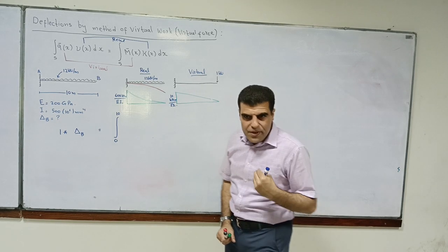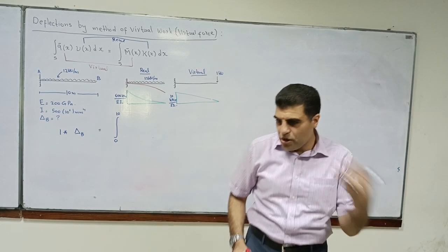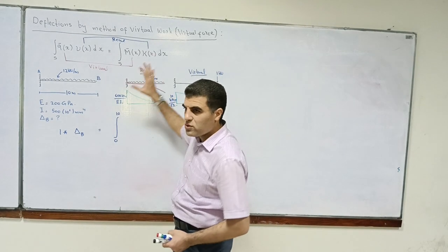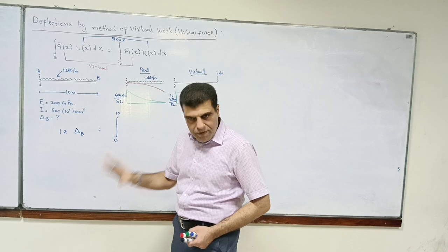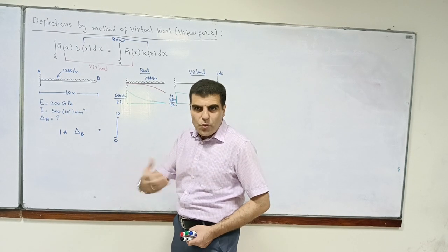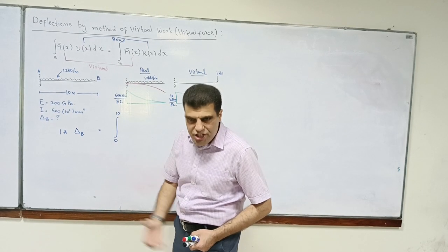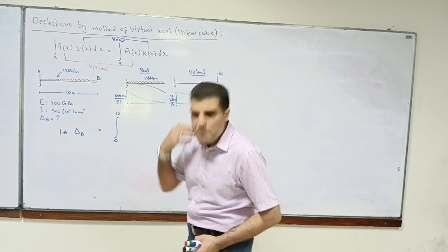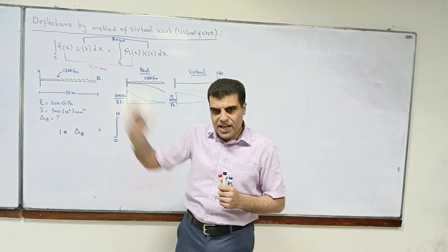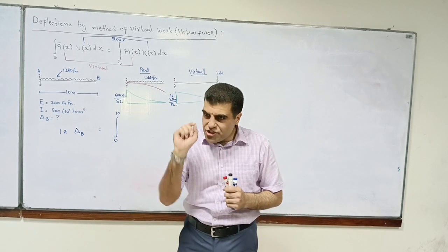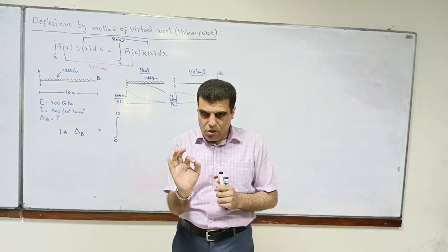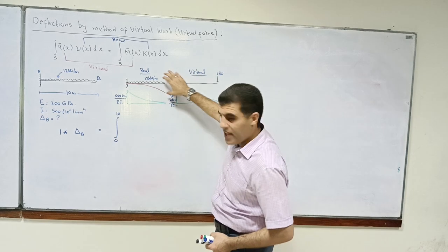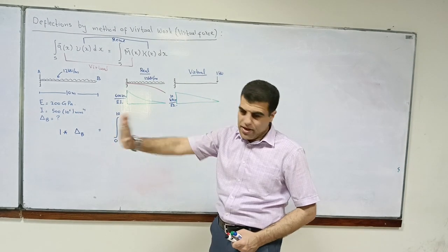You remember in your old classes or in your previous term, when you would be asked to draw the bending moment diagram or find the bending moment, you would work out the general bending moment equation, M of x, isn't it? And why would you determine it in terms of x? Because moment is varying along the length. It's not just specific to a point. It is varying all along the length. So a similar thing is true over here. Moment is varying along the x.